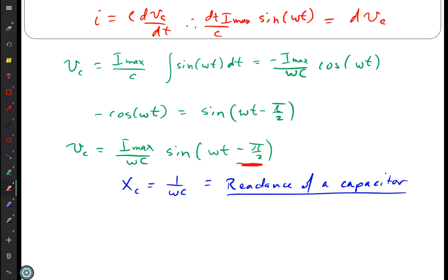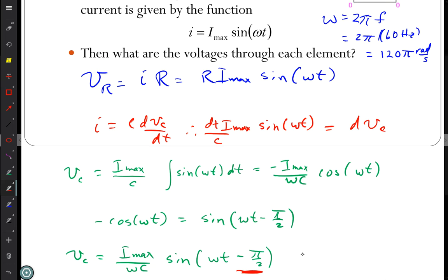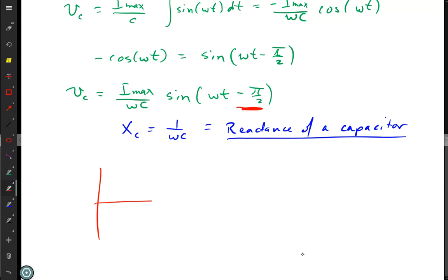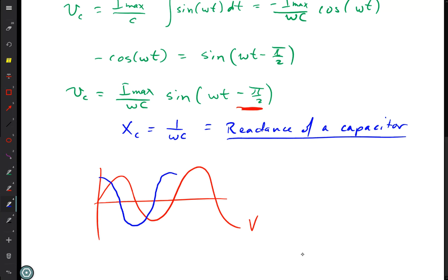What's the relationship between the two? Well, we can just look at this equation here: I equals C dV/dt. And just like I did yesterday, I can graph the voltage curve and then take the slope everywhere. So here's my voltage curve, and my current curve is just going to be the derivative. So the current's going like this. And now we have what is correct.